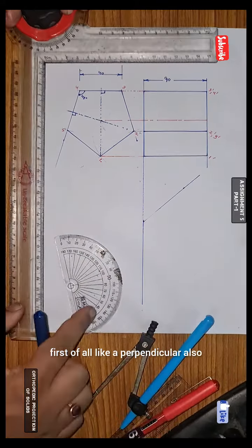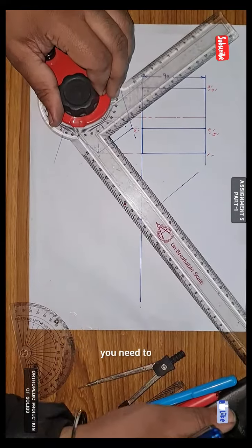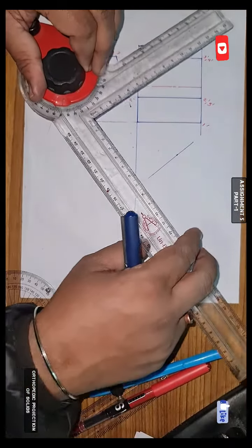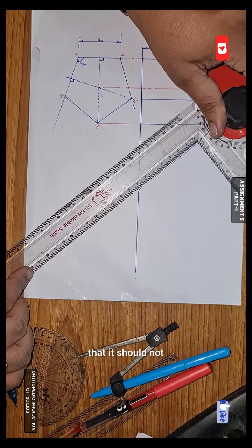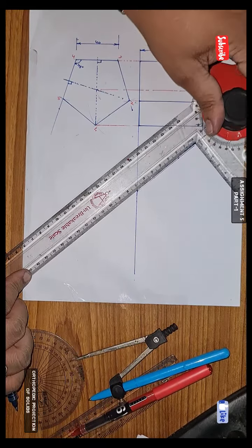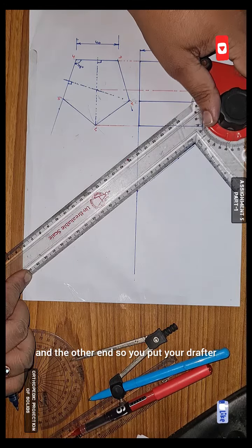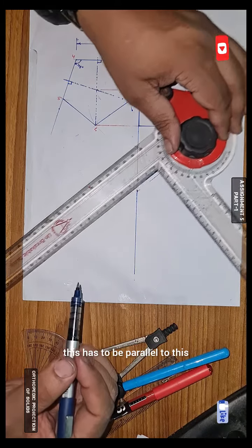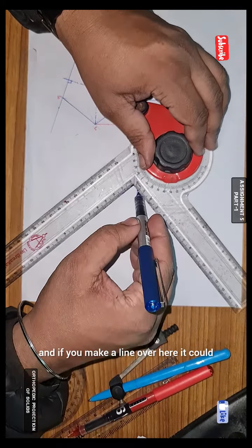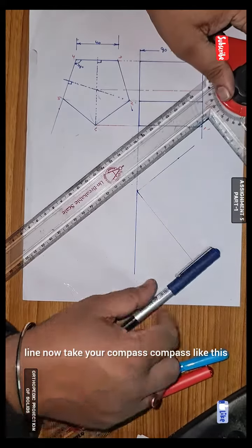First of all, make a perpendicular also. You need to put your drafter like this. Always remember that the drafter back should not be changed. So you put your drafter like this, and this has to be parallel to this, and if you make a line over here, it would become a perfectly perpendicular to this line.